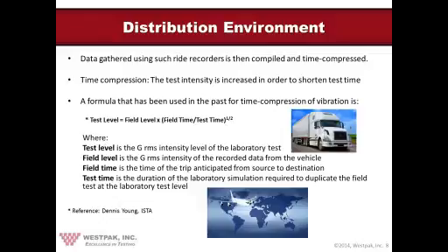Vibration is a great example of time compression. The levels measured during most of the studies that I've been a part of are about 0.05 to about 0.2 GRMS, and that's on a bad day, with the average being about 0.1 GRMS. However, some of these cross-country trips can take 3 days plus to complete. As much as test labs would love to do so, it's just not feasible to run a vibration test that long. Therefore, the calculated levels or intensity is increased in order to decrease the test duration. This is known as time compression.